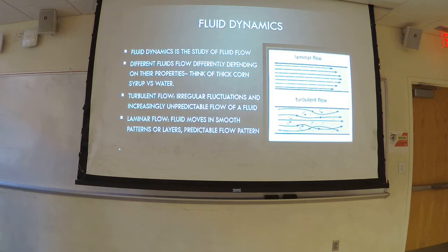Turbulent and laminar flow appear in many forms and indeed form somewhat of a sliding scale, wherein a fluid can become increasingly more and more turbulent. But there are some marked characteristics of each. Laminar flow is much more predictable, and the velocity is constant at each point in time. Whereas in turbulent flow, there are many irregular fluctuations and the velocity varies in both magnitude and direction quite wildly.